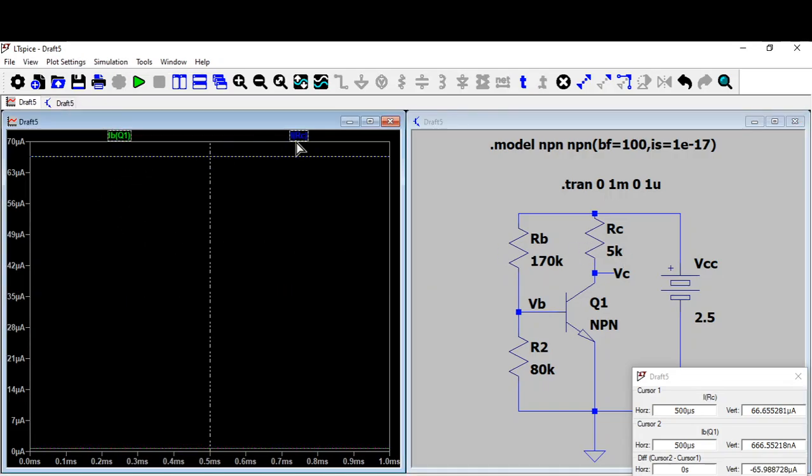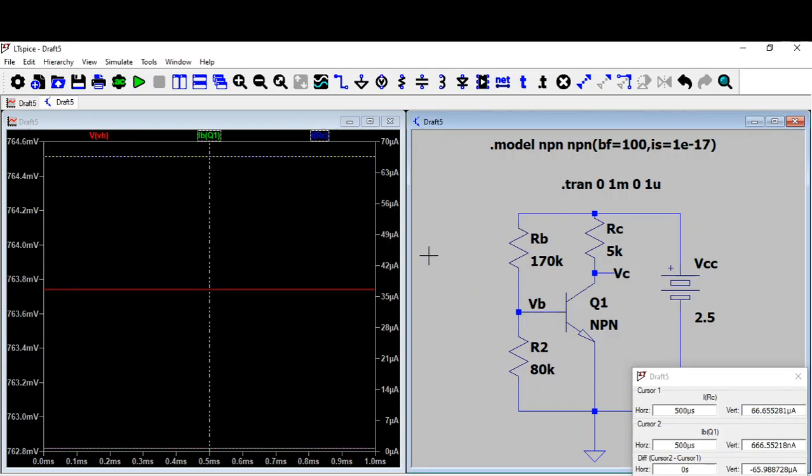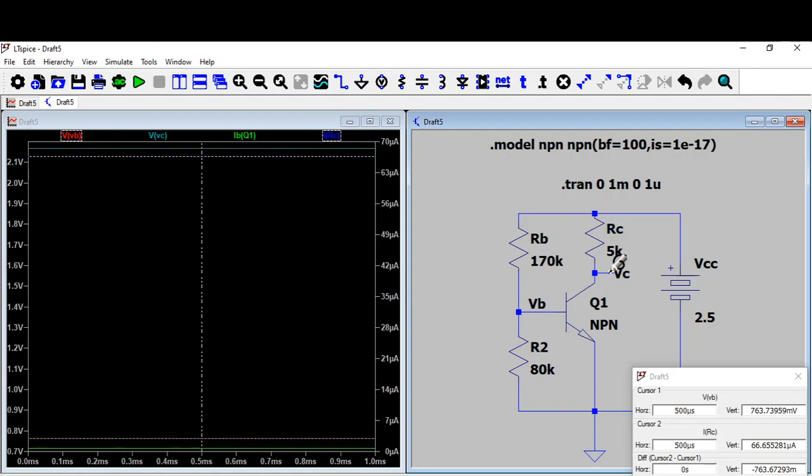You can see it's almost 66, so in simulation the current is 66 microampere, of course 66.6. The VBE comes out to be 763.7 millivolt, and then the corresponding value of VC in the simulation is...